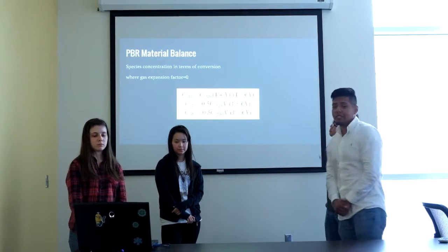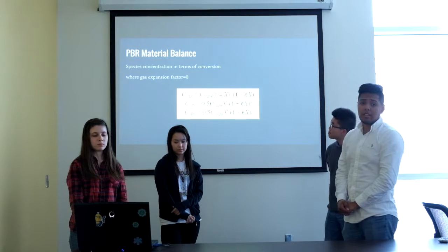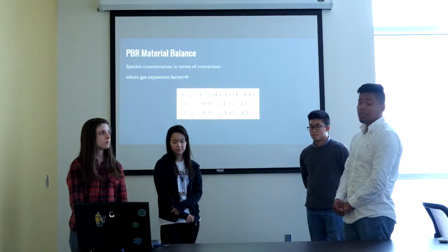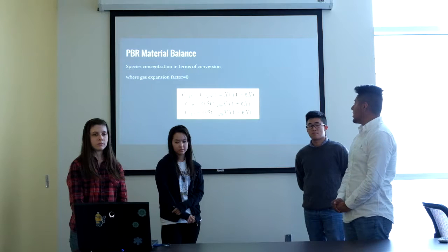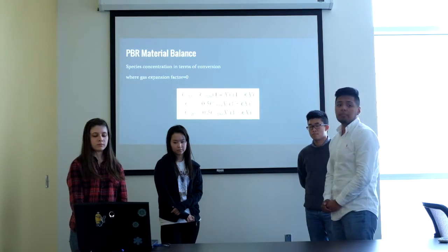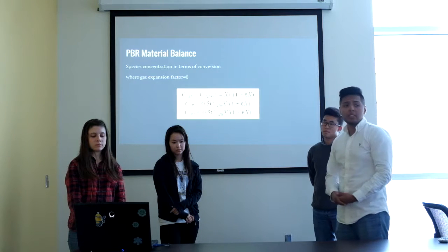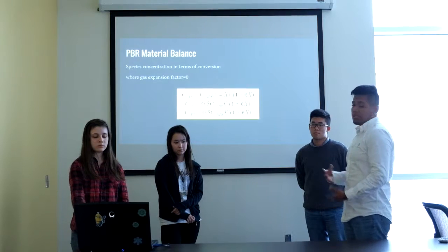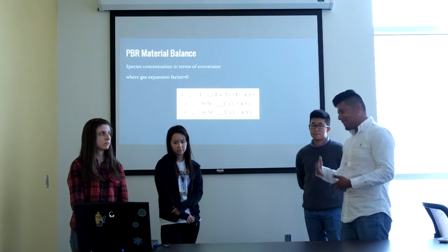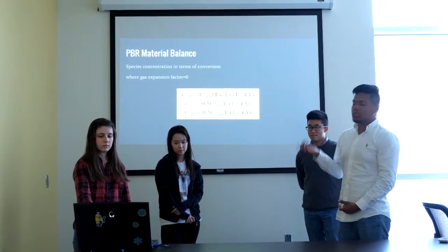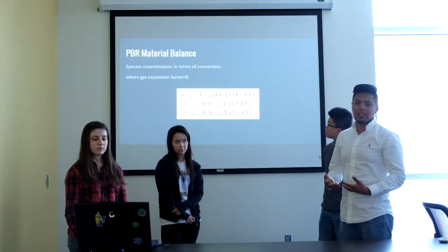Okay, so one of the first things that needs to be done in order to design this packed bed reactor is the material balance. And also we'll need kinetic data such as the rate of reaction of methanol and stoichiometric information, which is shown right here. So the concentrations of methanol, dimethyl ether, and water are shown here as a function of conversion and the gas expansion factor. The gas expansion factor ends up being 0 because we have 2 moles of reactant going to 2 moles of products, which therefore gives a delta equal to 0. And delta times the mole fraction will give 0, so the gas expansion factor will equal 0. Also, with this taken into account, the volumetric flow rate can be considered constant, even though we do have this gas phase reaction going on.